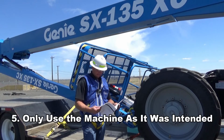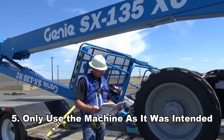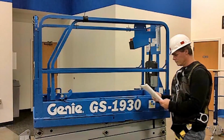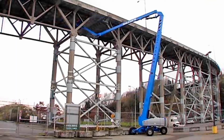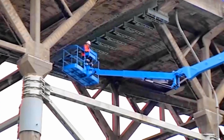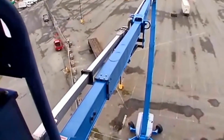The fifth key concept for safe machine operation is to only use the machine as it was intended. The operating instructions section in the operator's manual provides instructions for each aspect of MEWP operation. It is the operator's responsibility to follow all the safety rules and instructions in the operator's and safety manuals. MEWPs are designed to lift people and their tools to overhead work locations. The operator's manual will indicate if the machine can be used to lift materials. Using the machine for anything other than the activity specified in the operator's manual could result in death or serious injury. Only properly trained and authorized personnel should be permitted to operate a MEWP.